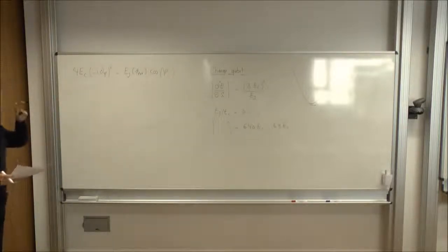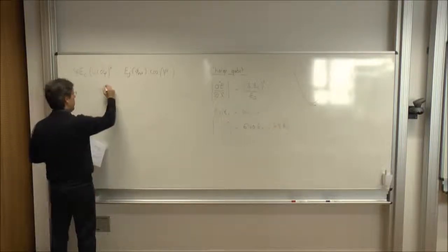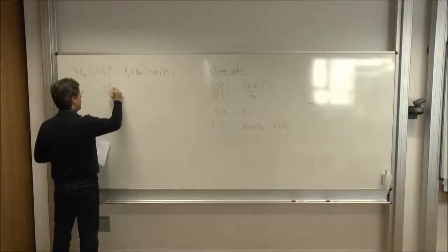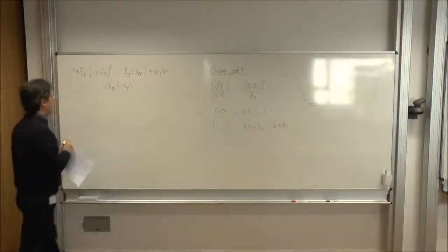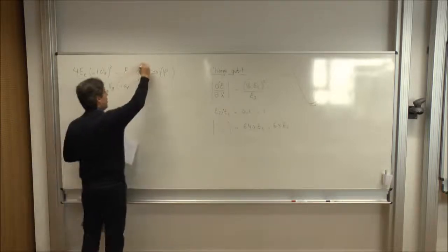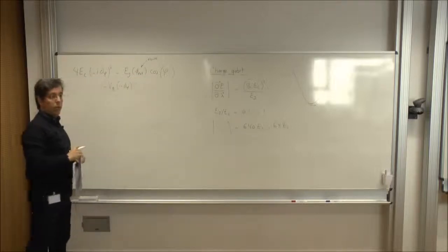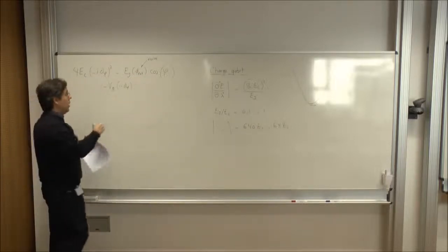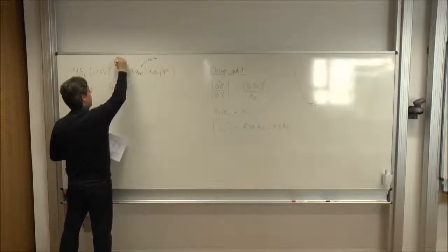So there are basically three sources of noise. One would be that you add to this some voltage coupled to this. So that would be one. The other one would be that you have noise in the flux you applied on the SQUID. And the other one would be that the Josephson junctions change.